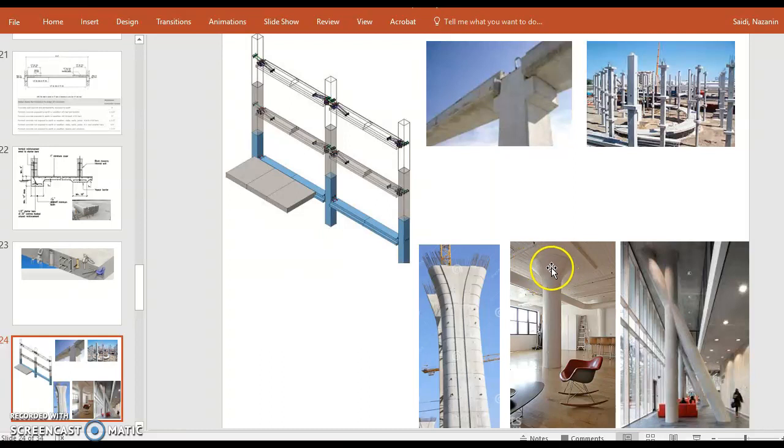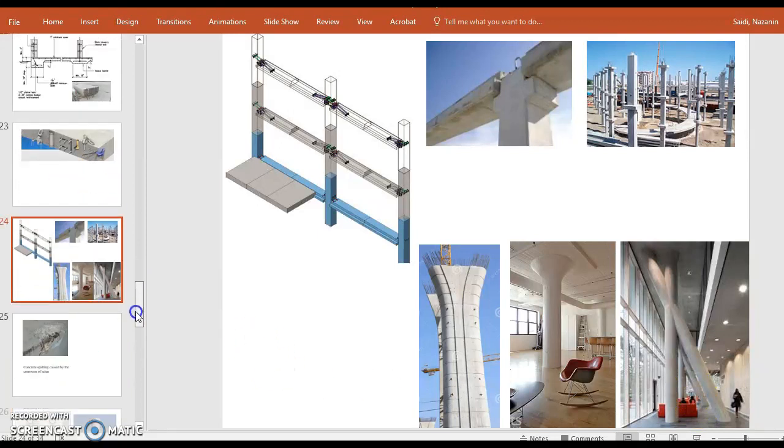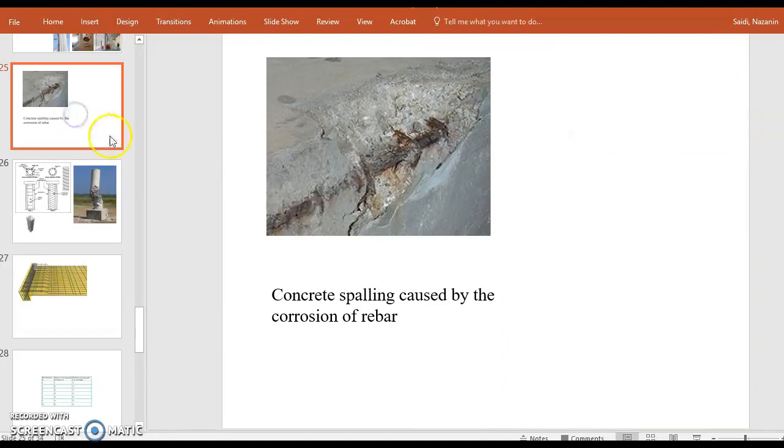So the upside down column is obviously very clear here. The two vertical and diagonal columns take care of the tensile strength and vertical compression strength. So although architecturally it creates an awkward space and removes some usable space, in terms of structure, this crisscrossing is very much needed for some types of structure.